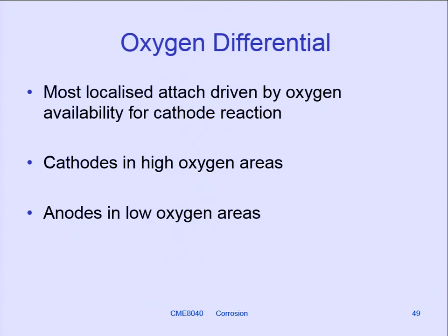Low oxygen underneath the pipe, relatively high oxygen in the solution above, and you got accelerated attack. They look like pits, but there's a long string of them, and there's a long string of them because of the capillary action in this sort of crevice arrangement.